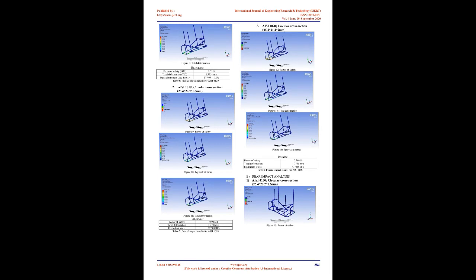2. Specification of frame. Based on the rule book considerations, inputs from other subsystems, and mechanical properties of the materials were considered. Hence, the design was finalized based on these parameters and made in SolidWorks. The analysis is done with the help of ANSYS 16. Based on the analysis, the modification was done, and the design was finalized. The material chosen for the chassis frame is AISI 4130 of 1 inch diameter and 1.6 mm thickness based on its tensile strength, cost, density, weldability, bending strength, and bending stiffness.